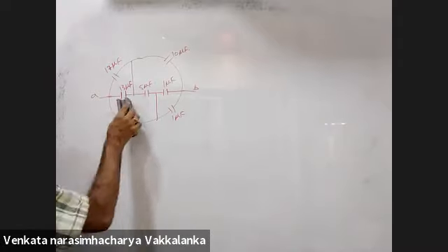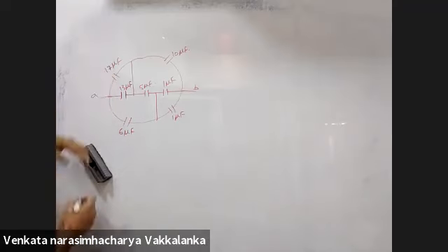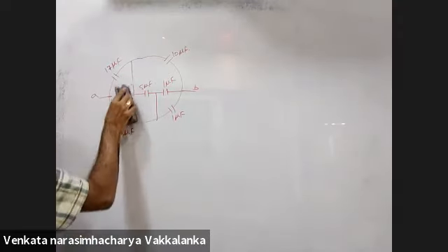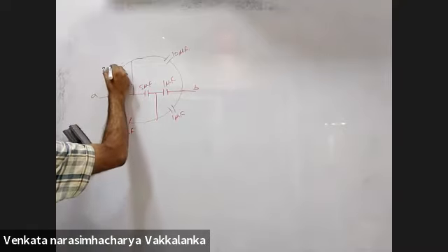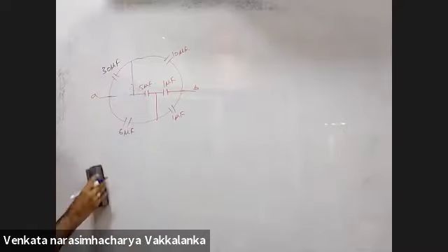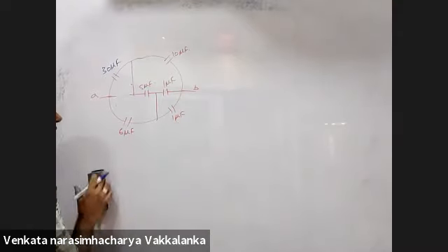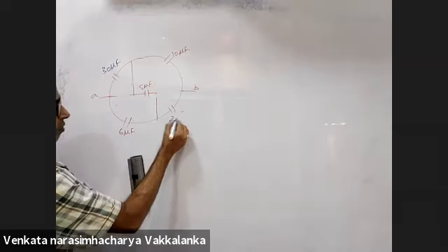Now I'll make changes here itself. Have a look at it. 17 and 13 are in parallel. Do you agree with that? Yes, sir. Because these two ends are connected, these two ends are connected. 17 and 13 are in parallel. This will become 30 microfarads. 1 and 1 are in parallel. This will become 2 microfarads.